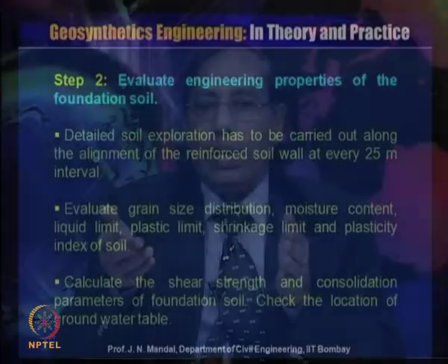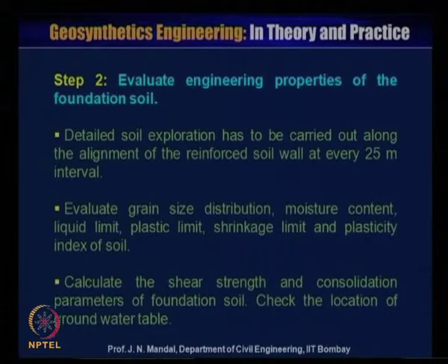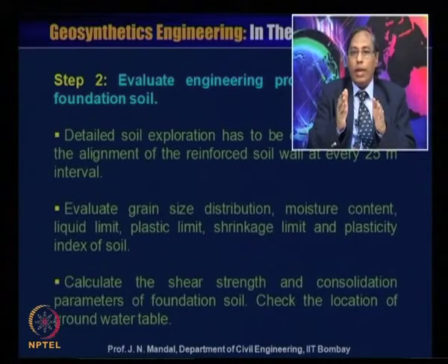Step 2, evaluate the engineering properties of the foundation soil. Detailed soil exploration has to be carried out along the alignment of the reinforced soil wall at every 25 meter interval. It is necessary to carry out the test. Sometimes you can obtain some result without any soil exploration. It will be a danger. So it is very important that one should carry out the test along the alignment of the reinforced soil wall at every 25-meter interval.